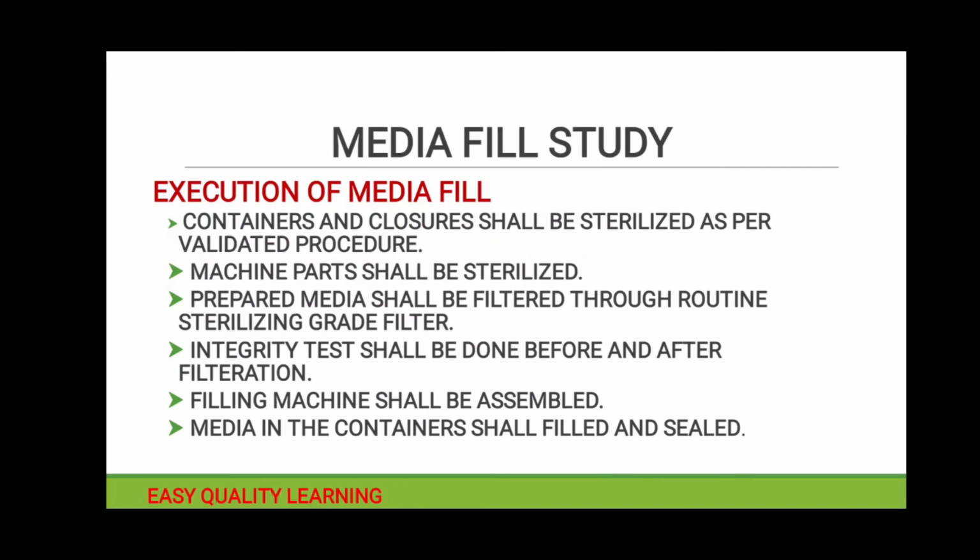Machine parts shall be sterilized as per the routine cycles. Prepared media shall be filtered through routine sterilizing grade filters. Whatever sterilizing grade filters are used for our routine commercial production, the same filters shall be used for your media fill also. Then integrity test shall be done before and after filtration.